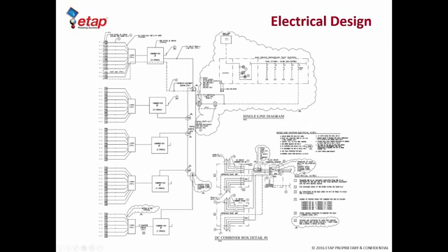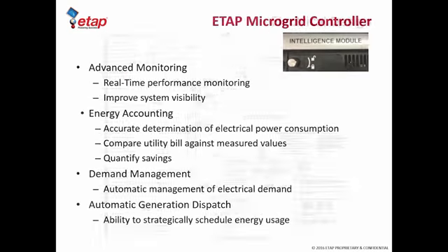So we opted for a 250 kVA grid-tied inverter, and that goes essentially back into the main switchboard that's fed by the local utility here, which is Southern California Edison, and that's a step-down transformer, which is the main service entrance T1, and that's a 750 kVA service, 11 kV down to 480 volt service. So that's basically the overall setup of the system, and we'll see the same thing on the ETAP side.